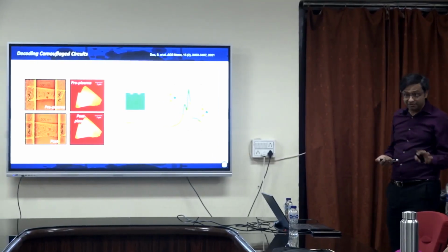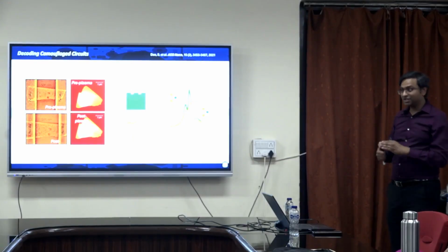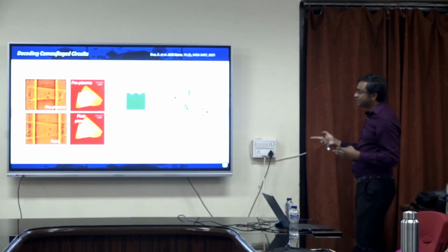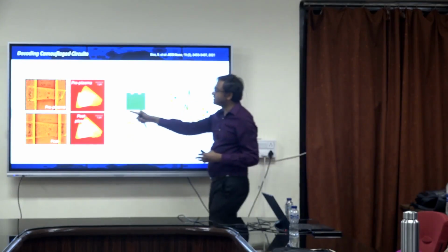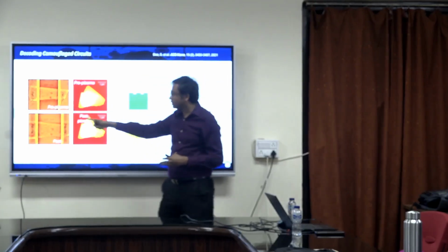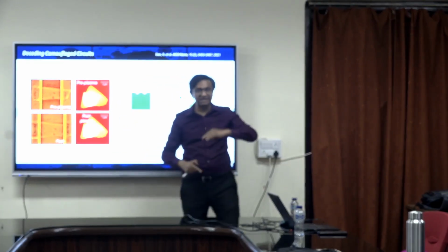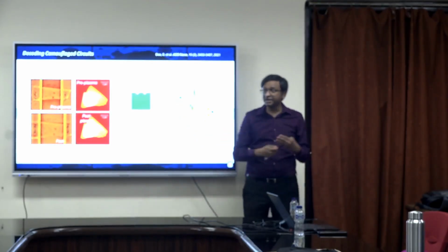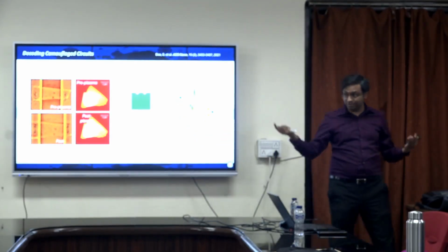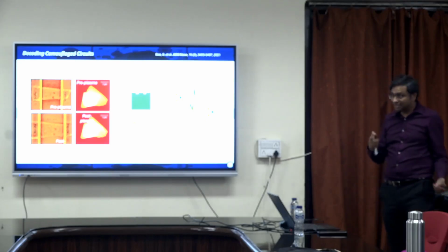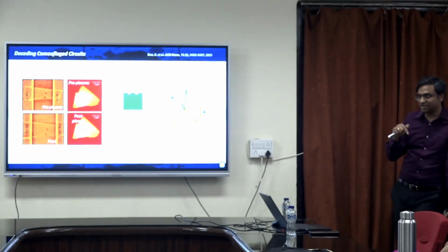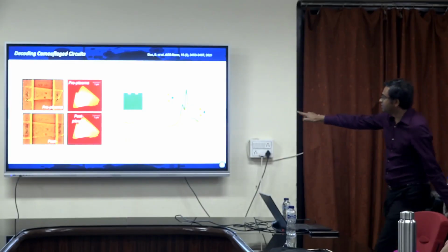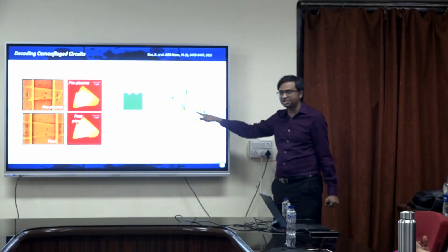The only way to find out whether there is something going on, you can now start taking some SEM images. You can start doing some AFM because the height will be a little bit different after the oxidation, right? Or you can even do, let's say, Raman or PL, correct? And then you can find out that, oh, this material has been oxidized, correct? Material characterization. You see pre and post plasma treatment, the Raman shift is there.